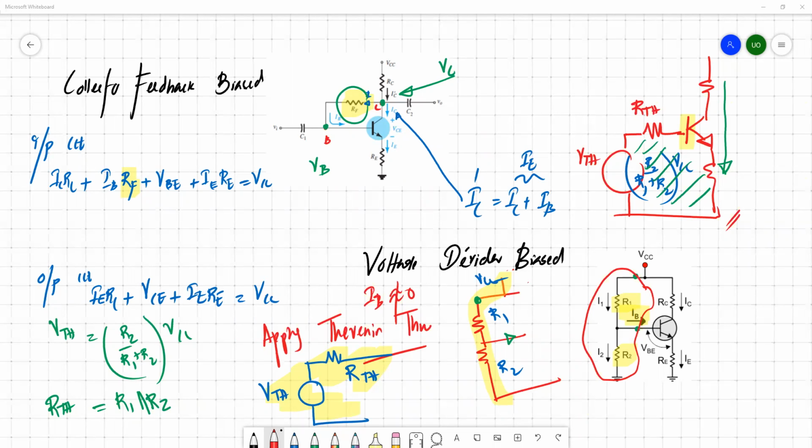So how do you do the DC biasing? First, stick into a kind of biasing circuit. Then you can select the transistor, and accordingly select the data sheet and the relevant parameters like supply voltage and the operating regions. According to the circuit configuration, you can derive the DC load line and overlay this DC load line on top of this device characteristics.